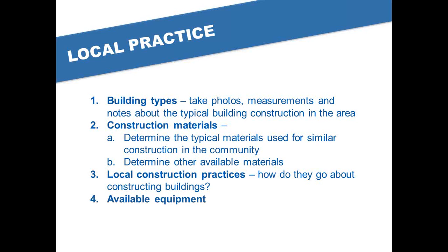And then what available equipment is there for doing this? You know, it's not like you can always order a crane. How big a thing is, how are you going to mix concrete? You're most likely not going to get a ready mix truck to your site, but can you rent a small mixer, or are you just going to be doing it on the ground using a volcano method? And then what is the availability of skilled and unskilled labor? So all this you'll learn at the site and take into account as you're doing your design.